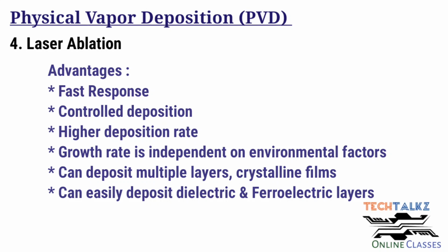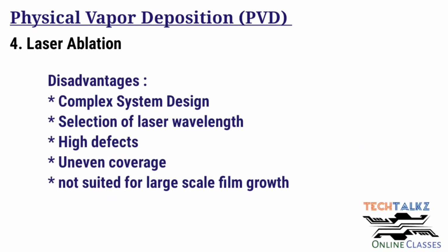There are also some disadvantages. It is a complex system design. We need to select a particular laser wavelength for each target material. There will be high defects, uneven coverage, and it is not well suited for large scale film growth.